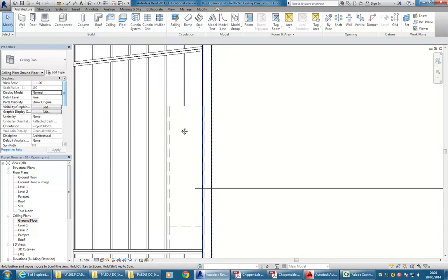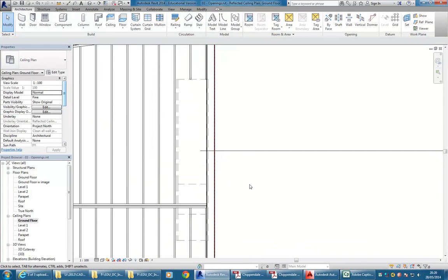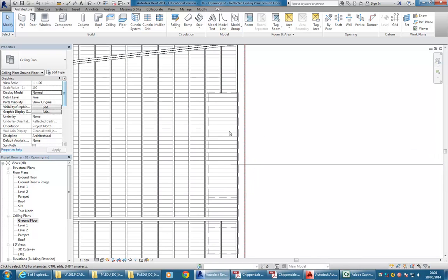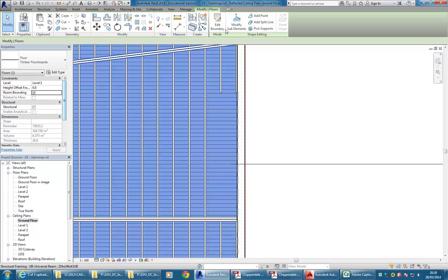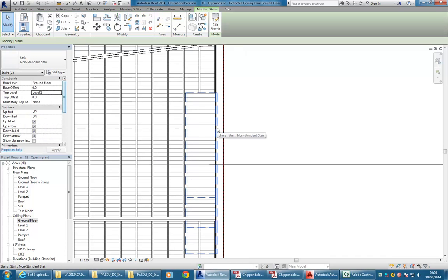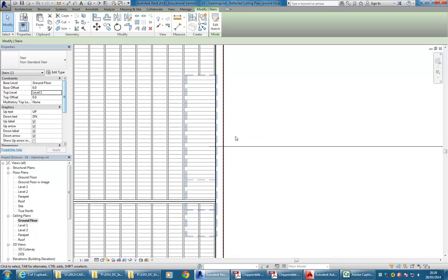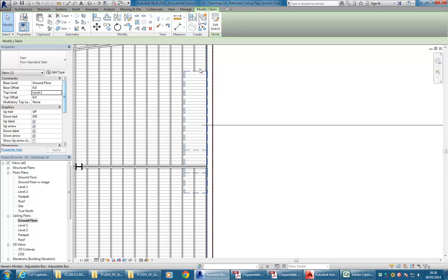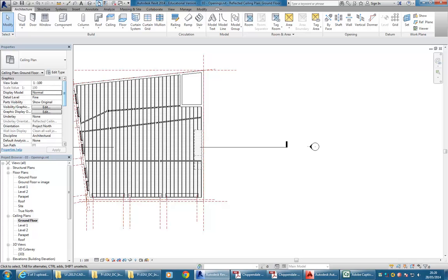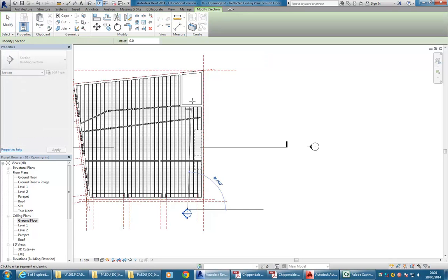Okay, so I've made a gap in my floor structure for the stair, but then I need to also cut a hole in the floor itself. So select the floor there. How do you know how much space you'll use? I'll just cut around the stair. All the way around? Yeah, right around the edge of it. How many stairs do you have to come up? Well, here we know because we've got the beam there, so we'll just leave all of that room. But if you need to work it out, that's a really good thing to be thinking about, because that is exactly the process you'd go through.